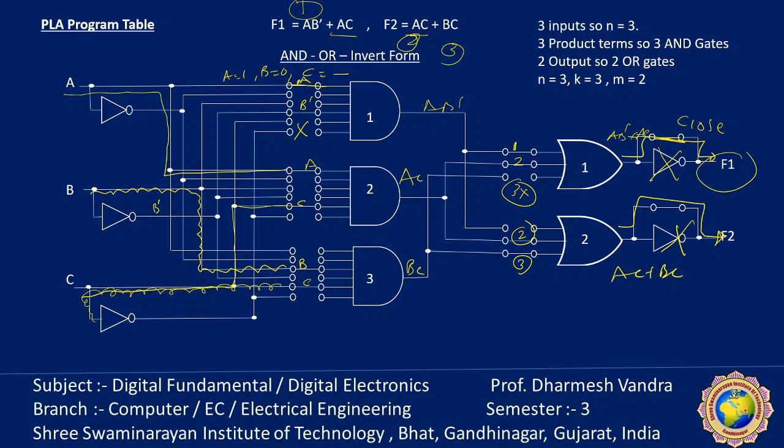So simplify each function in minterms. Okay, the internal parts of PLA for this circuit, as I already explained, when we design the digital system with PLA, there is no need to show the internal connection of the unit. As I already explained, only the PLA table is required and it is assumed the appropriate path is supplied. When implementing a combinational circuit with PLA, careful investigation must be undertaken in order to reduce the total number of distinct product terms. So here, in comparison with the OR gate in ROM, there is 2^k times n required, and m's are all product terms, while here only the required product terms, only 3 product terms, are there.